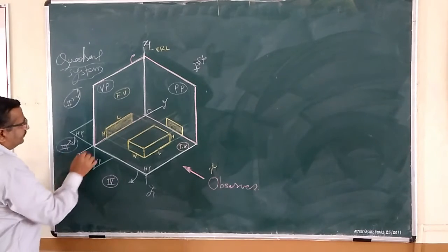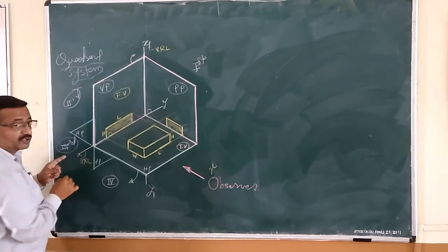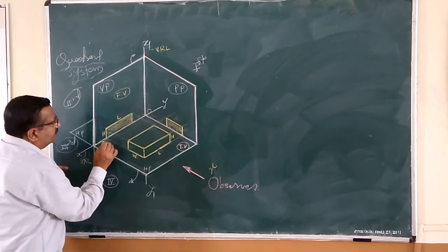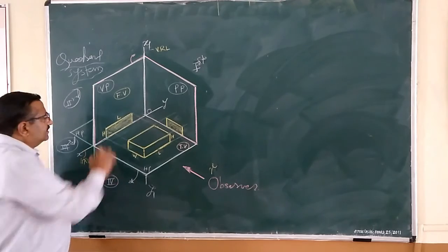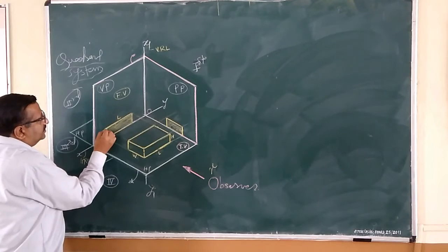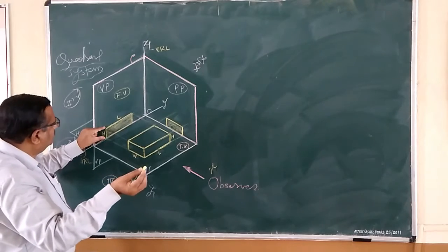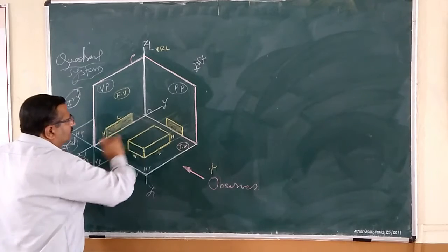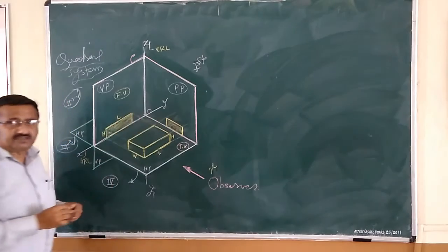So this baseline has cut this XY top line, and we have extended the line to the point of intersection of this projector. Just project it up. That projector will yield us the desired corresponding height of that object. So this much distance is nothing but the height of the object. Now what I have to do, in the way I have constructed this parallel to the right 30 degree line, I have drawn one line projecting this way.